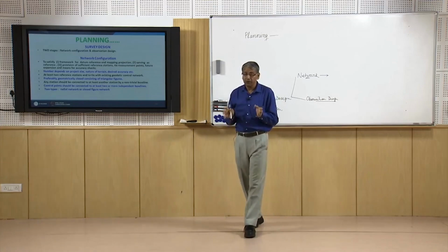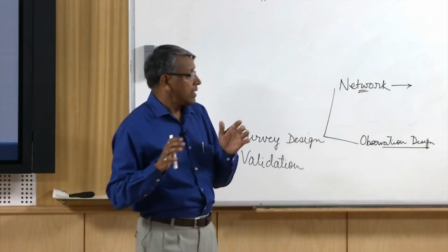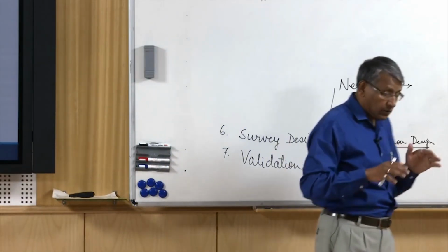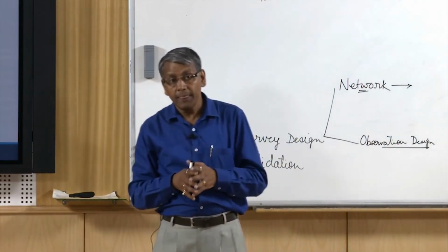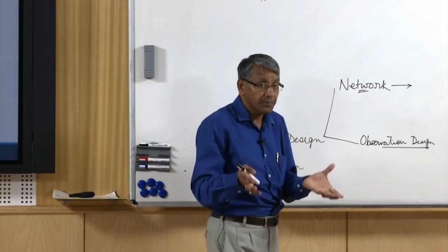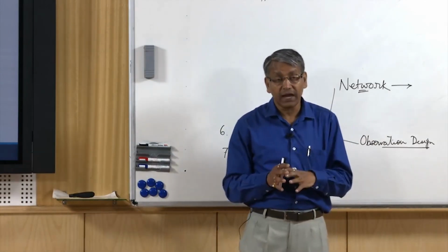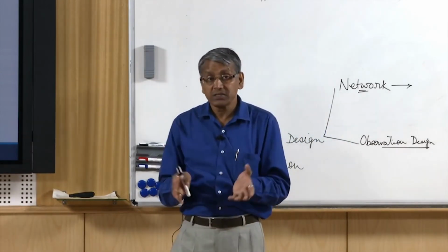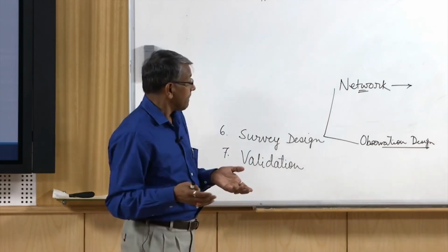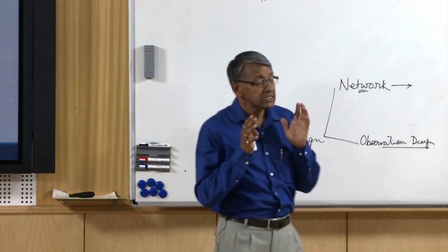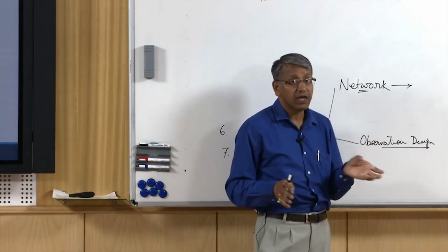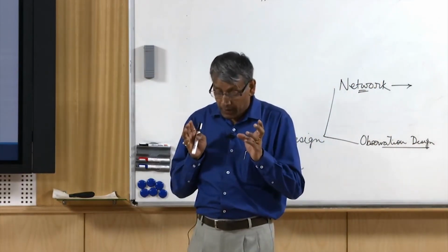So the number of stations to be selected within a project area will depend upon the extent of the area, the nature of the terrain in which the project will be carried out, as well as your positioning methods, and finally the accuracy or the specification that the surveying has to achieve.